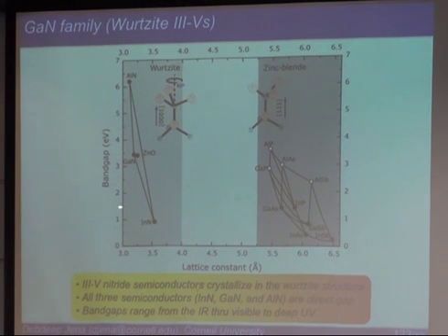But the major differences in electronic properties, first things first, are that the band gaps are generally quite a bit larger. Gallium nitride is 3.4 electron volts, aluminum nitride 6.2 electron volts. Indium nitride is actually kind of small, 0.7 or 0.6 eV. There was a big controversy with the band gap of indium nitride. Till 2001, everybody thought the indium nitride band gap was 1.8 electron volts.